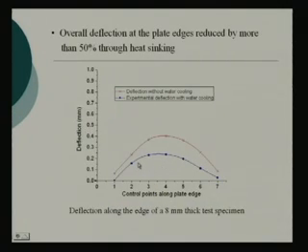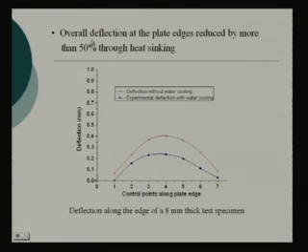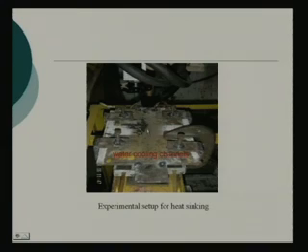What was found out, of course, is to verify what exactly is happening, and also you develop your theoretical model and see how much it is matching. Here you can see it gives us almost 50% reduction of distortion. This red line is deflection without water cooling. That means the same plate geometry was welded without this cooling, and next the same plate geometry was welded with water cooling, right.